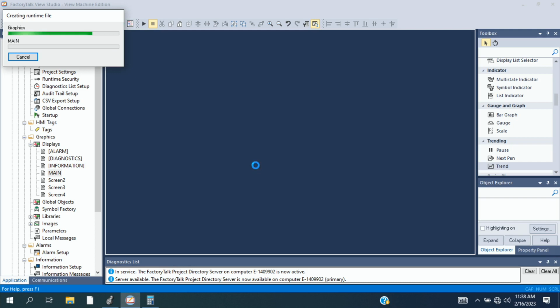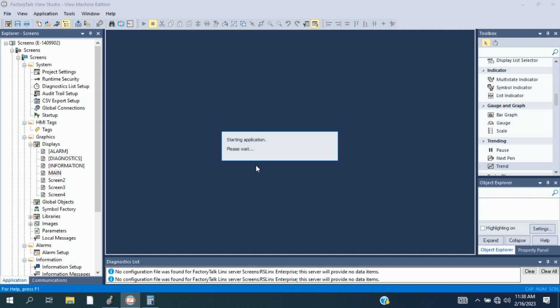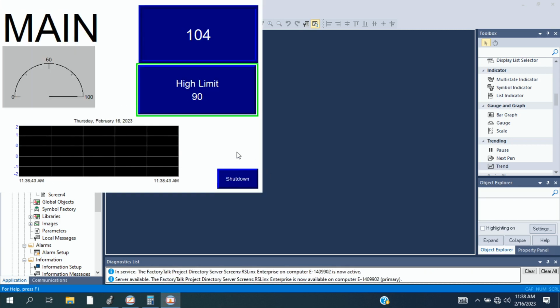It's neat to be able to see the graphical data, the trends, variables going up and down, especially if you're monitoring things. A lot of these analog inputs are monitoring things like temperature and pressure, distances. There's so many different types of sensors that could interface with this. So there we go. We can see our graphs are updating here, so I'm going to rotate that analog input. The bar graph moves, and I think the scale on the trend line tends to move up and down.